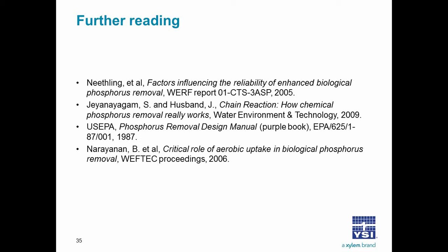So what might be a practical strategy is, for example, adding chemical to return streams. Centrate, for example, may have high concentrations of phosphate, or adding chemical at the very end of the process to remove the phosphate further than what the biological process might be able to do alone.